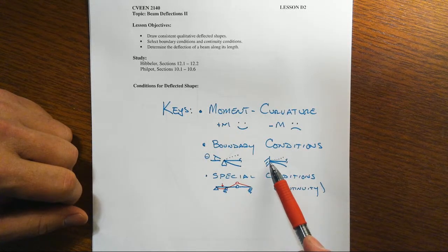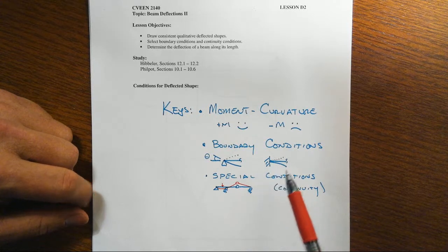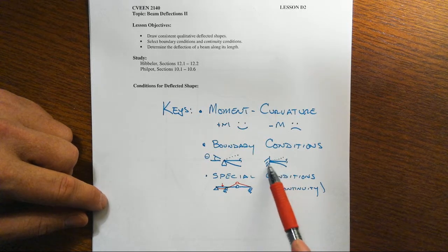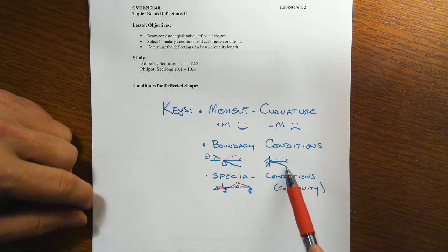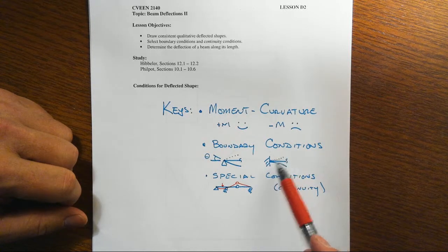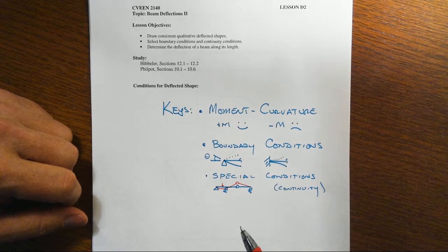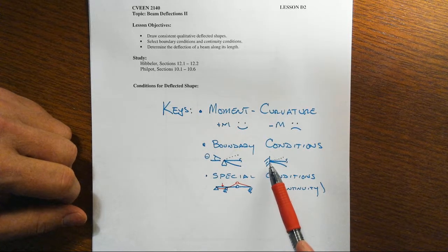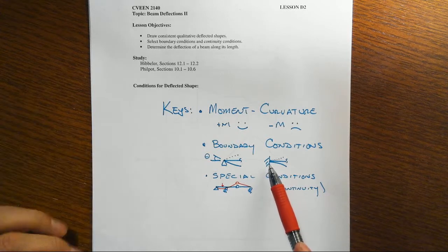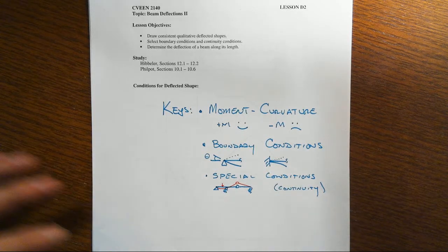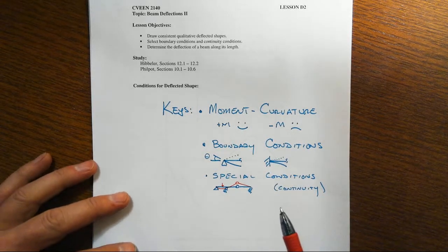Whereas the fixed end is going to have absolutely no translations and no rotations either. So the deflected shape, whether it's frowny face negative moment as shown here, or the dotted line being the positive bending moment, when it comes in right at that support it should have absolutely zero slope, no change at all in what happens at that location. So that's just 2 examples of boundary conditions.